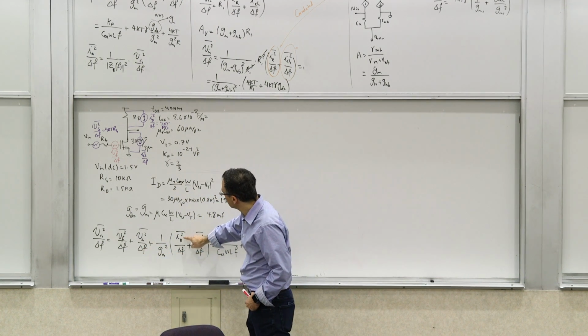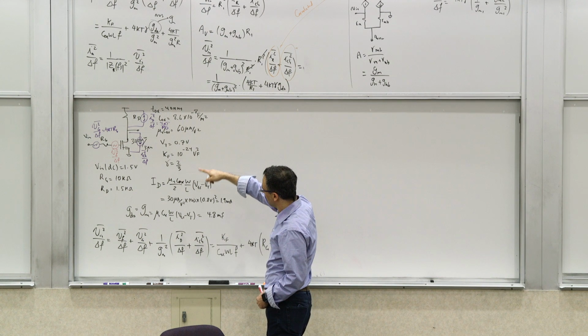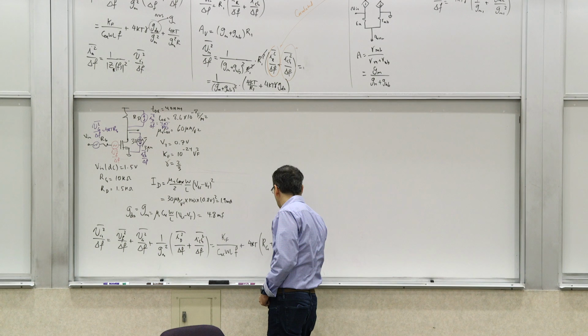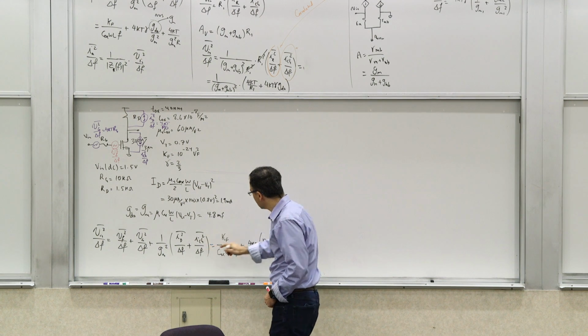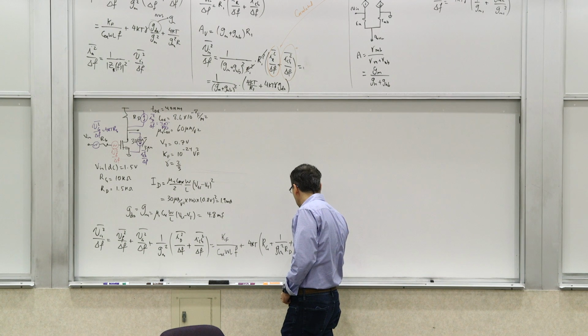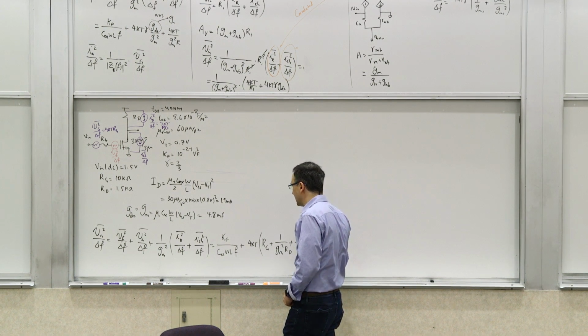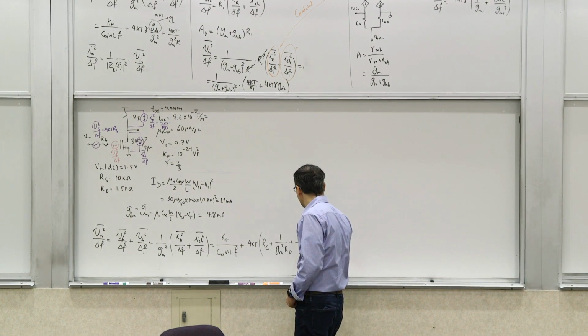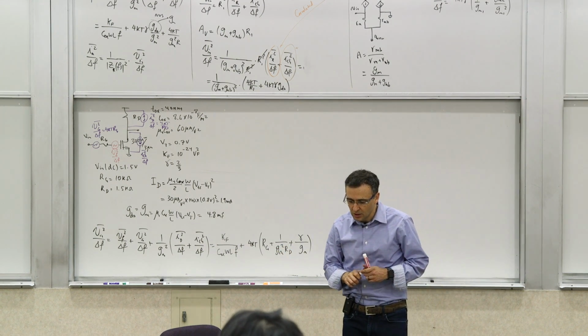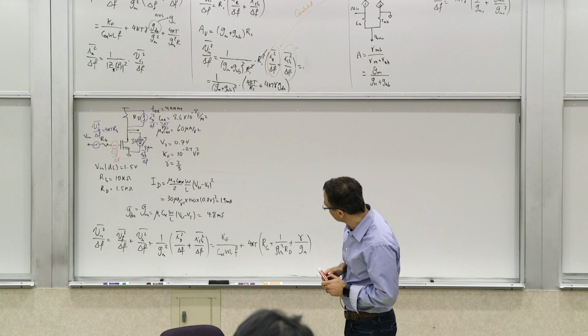Then from this, the resistor noise is 4kT over Rd, so that becomes Gm squared Rd. And then you have this guy, which basically has the 4kT, so you have gamma over Gm, if it's non-velocity saturated, right? So those are the 3 sources that you will see.